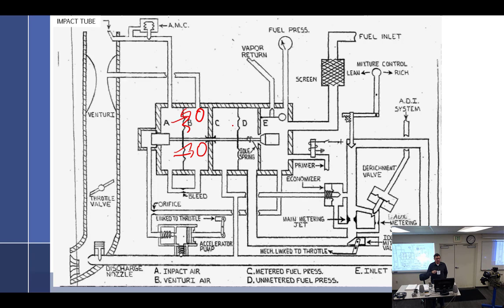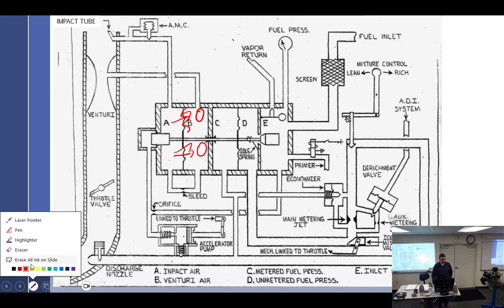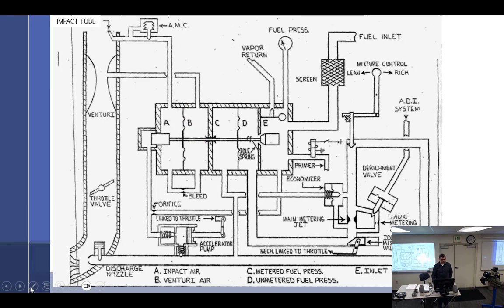So I try to give it some throttle. What is it going to do? It's going to run. The more throttle I give it, the leaner it's going to get until it doesn't like it anymore. So if that diaphragm breaks here, then what happens? Only idle works.